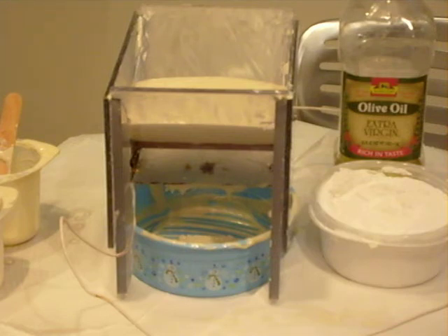Also, as we mentioned earlier in our presentation, we did have a problem of shorting. This is very important for ER fluids because you have to deal with the dielectric breakdown strength of the fluid, which is something you don't have to worry about with an MR fluid. You also have to worry about the electric insulation of the electrodes from the fluid and also from the container containing the fluid, quite possibly.